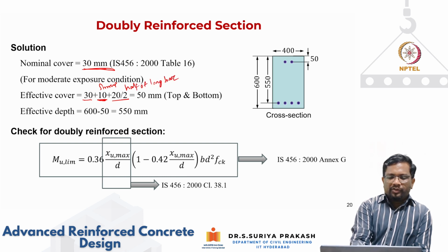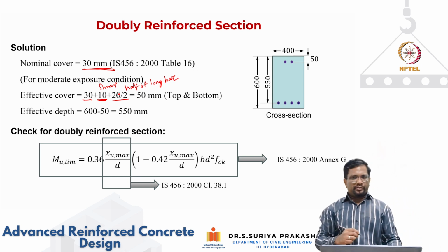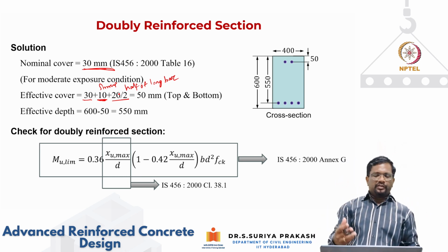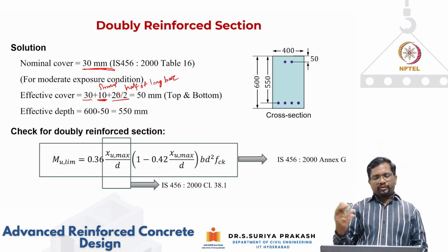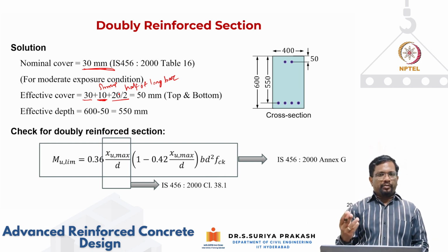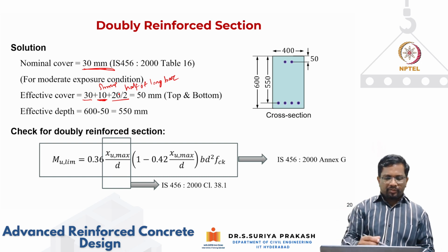So I'm assuming that I'm going to use 20 mm bars. Sometimes we may have to revise this also. The number of bars for 20 mm may not be adequate, so you may have to put 28 mm, or 30, 32 mm, depending upon your requirement.